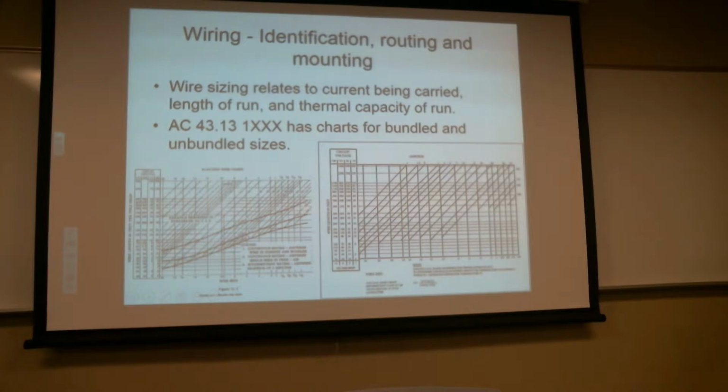The STC should include all of this data, and it will be approved data versus acceptable data. Now, they might have copied everything from here, but you don't care. All you care is it'll say, run a wire from here to there, for that length of wire use this size of wire, use this size circuit breaker, route it this way. This is golden, this is great. You've got a whole bunch of approved data.